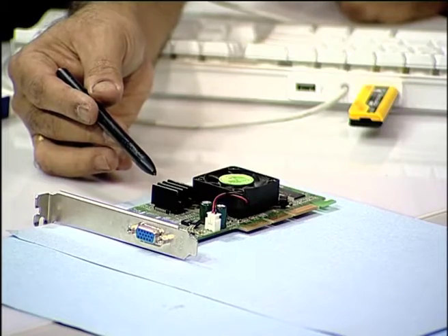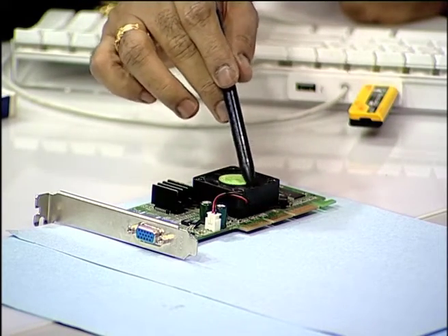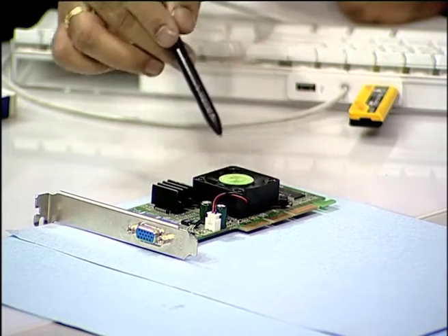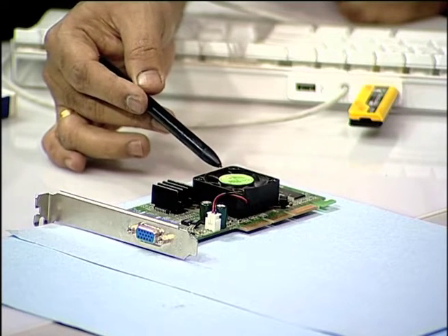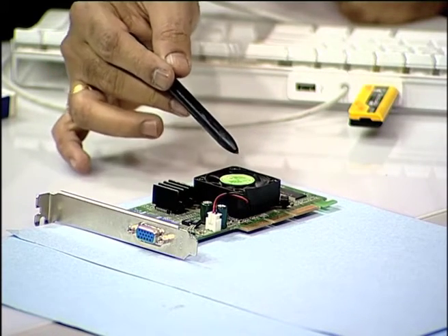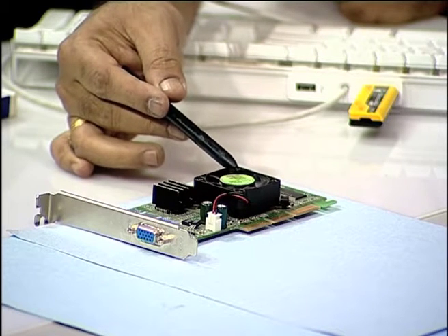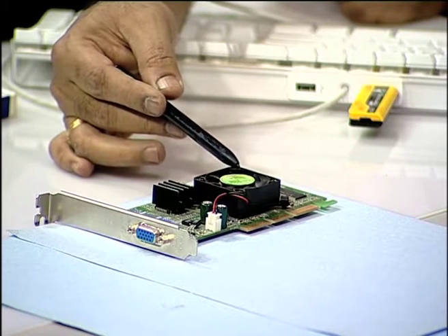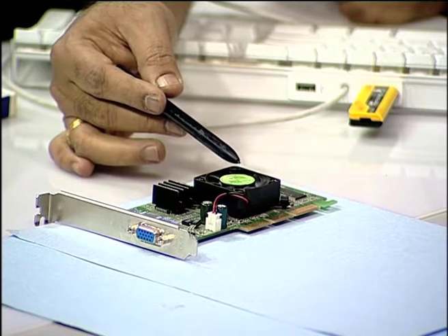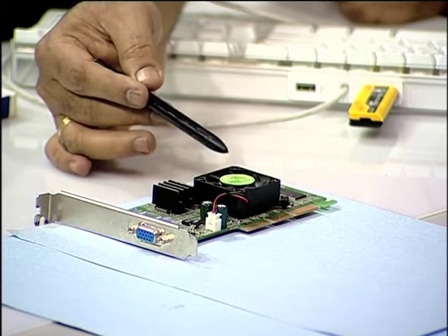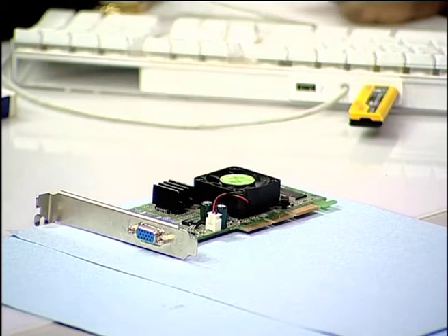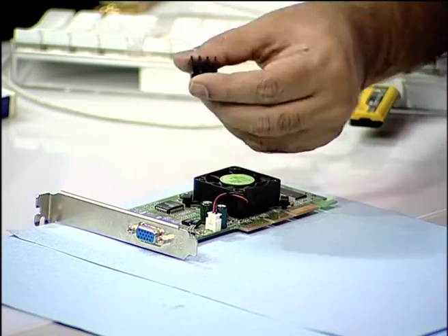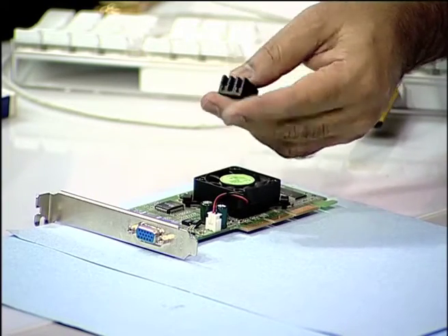In other cases, you can also use a fan. You can see here in this case a fan is used on top of an integrated circuit. Obviously, this material is lightweight, but it is positioned in such a way that it is mounted on top of the active device to remove heat. So, in your thermal analysis, you will have to carefully look at whether you require a heat sink or a forced cooling method like a fan, or you do not require these at all if it is not a major problem.